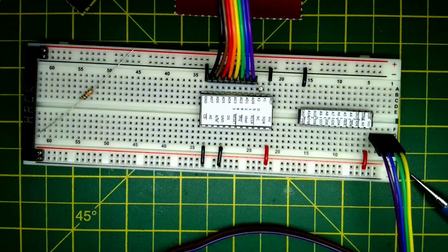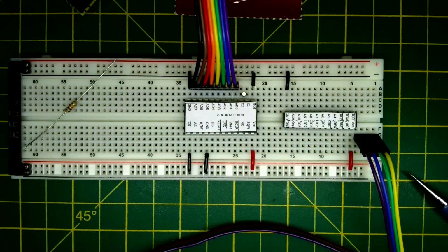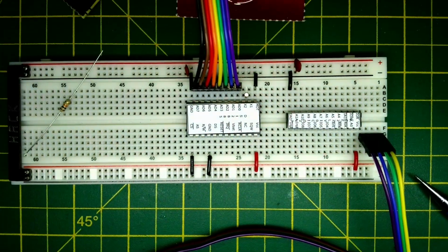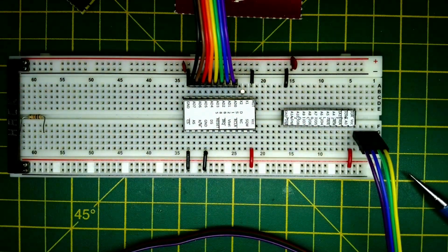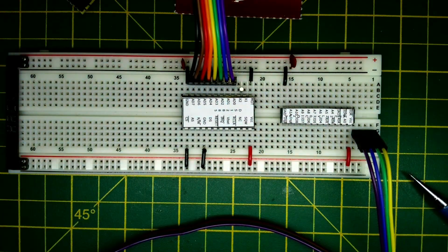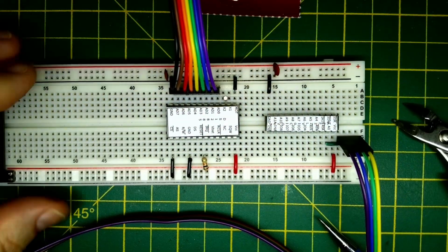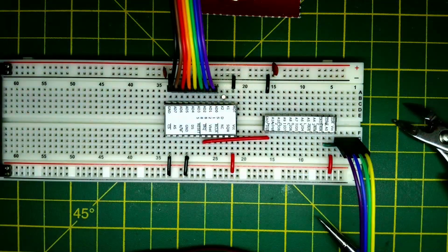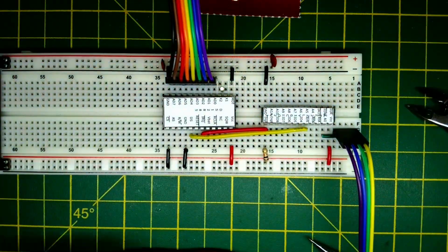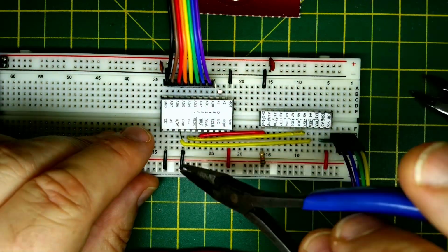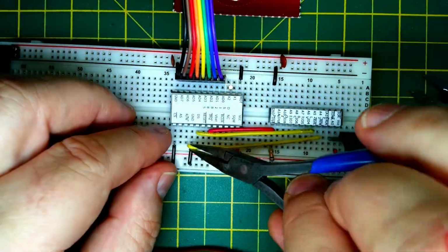Another ground there, that's used to clear the CMOS RAM. Now we've got the pull-up resistor here, but in fact we need to move it over to the right so we can fit the battery in there. I actually realised I needed to move that over there. Then putting in the RTC read, write and address enable, address strobe.